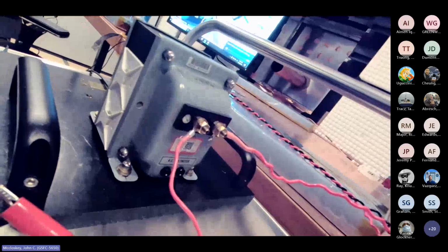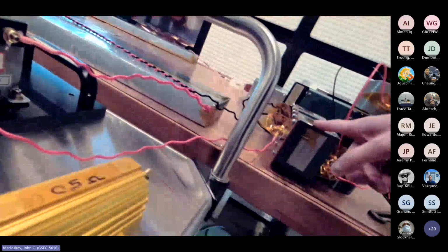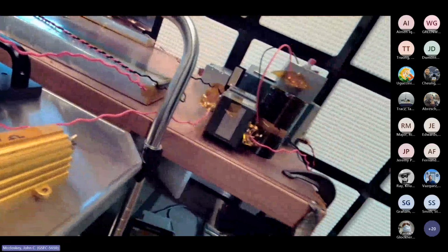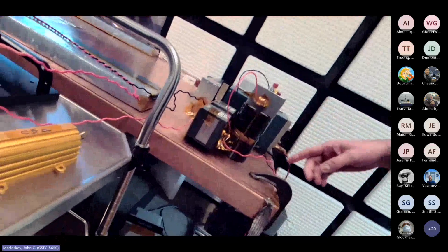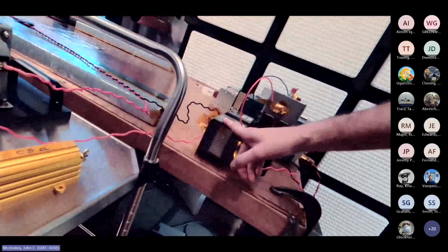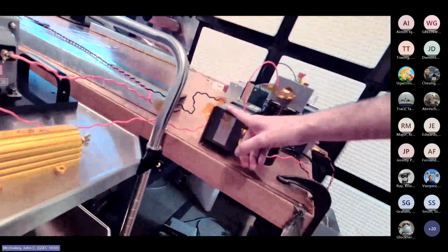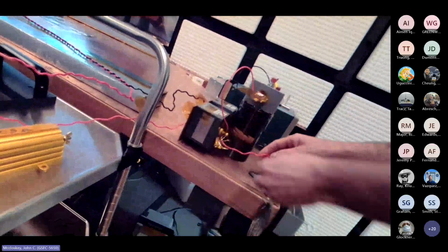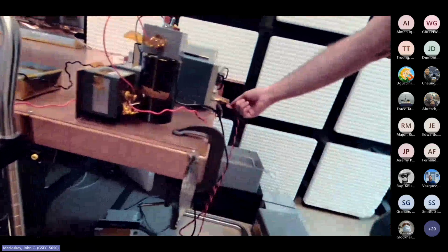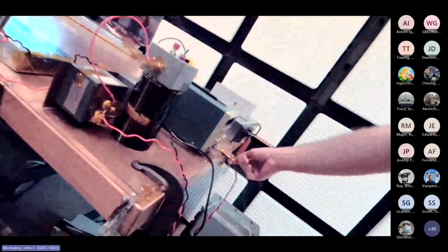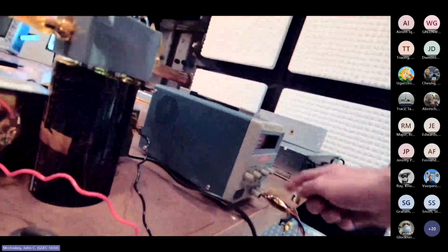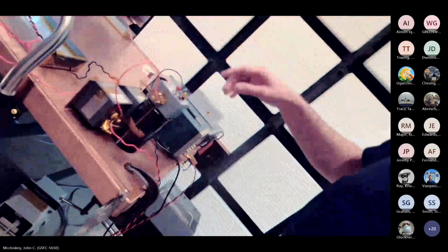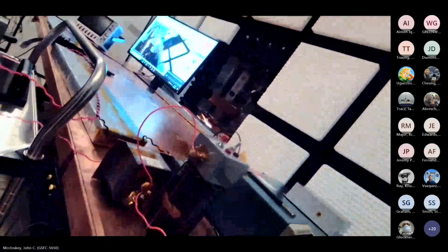So you're positively coming off the capacitor network and generally going all the way back to the power supply, right? Don't just trust that it's a red wire. We've been bitten by that before as well. So the red wire is going to this capacitor, going to the red wire that's going to the positive terminal of our power supply. Then the black wire from the power supply going to the other capacitor to the black wire. Oh, there you go. Okay.